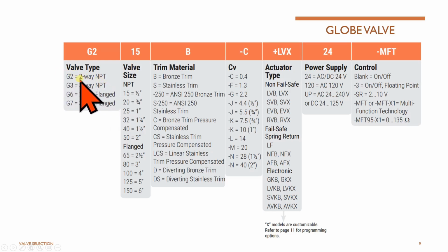So based on that, you can select the valves here, and based on the valve size, you can select in one of these, and what has been specified in the specification with respect to what the body should be, what the trim should be, and what the close-off rating should be. Based on all of that, you can determine what actuators you should use.